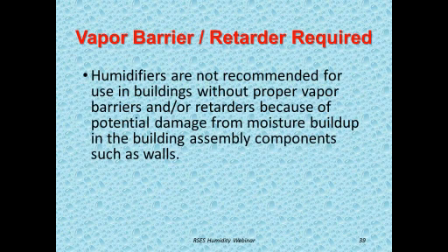Humidifiers are not recommended for use in buildings without the proper vapor barriers or retarders because of potential damage of moisture buildup. I mentioned it's going to get below 0 tomorrow night. You can be very sure if I did not have a good vapor retarder that moisture from my house would go into my walls and actually condense when it got near the outside of my walls. And if that happens frequently, it's going to rot out your studs, rot out your plates.